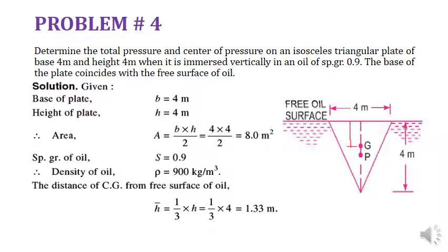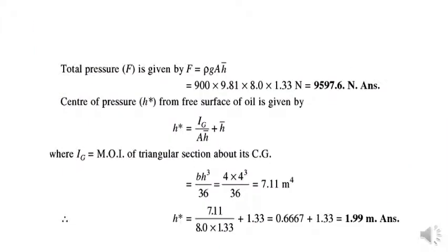the depth equal to 1/3 of it. So from the base of the triangle, this distance of the center of gravity is 1/3 of h, and the rest of the dimension from the top or from the tip will be 2/3 of h. Okay, so you need to be very careful about that. If this triangle were inverted, the value of the h bar is also going to be inverted. So in this particular case, it will be 1/3 of h.